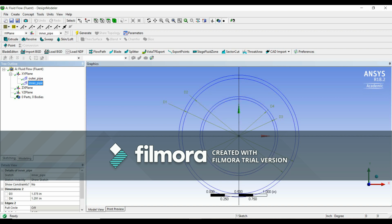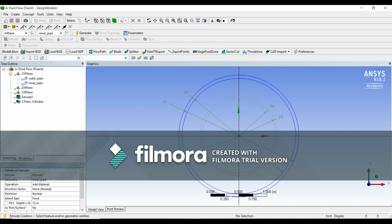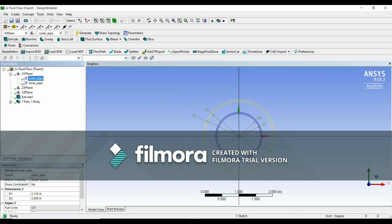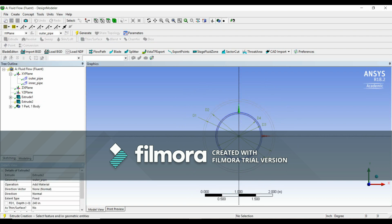We're going to do the extrude command for the inner pipe. We're going to add frozen, and then we're going to extrude at a depth of 240 inches. Then we're going to also extrude the outer pipe. We're going to add frozen also for that, and then extrude that also for 240 inches.